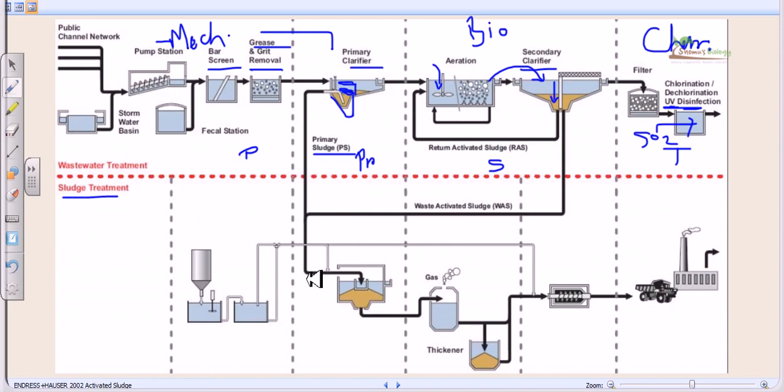So what we have seen in this case, we take the sludge, we digest the sludge. Now what we mean by sludge digestion is that we have huge pipes and pumps. We utilize heat, and we utilize a small amount of bacteria which are present in the sludge to digest the sludge anaerobically, and as a result of this anaerobic digestion, they produce methane gas. In this process, we utilize a small amount of microorganisms which are methanogens. Now we know the action of methanogens, that they can utilize carbon sources and generate methane gas.